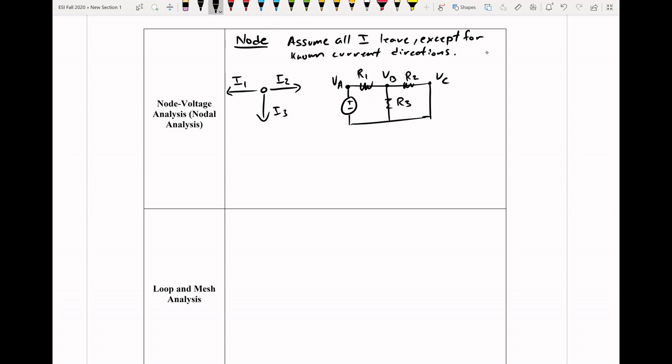Okay, something that we have to have for a nodal analysis is a thing called a ground. And what the ground gives us is a point of reference. And what we want to do is to select a point that will help us out the most. So if we look at the bottom wire here, you see that there's a point that all three of these wires connect to.